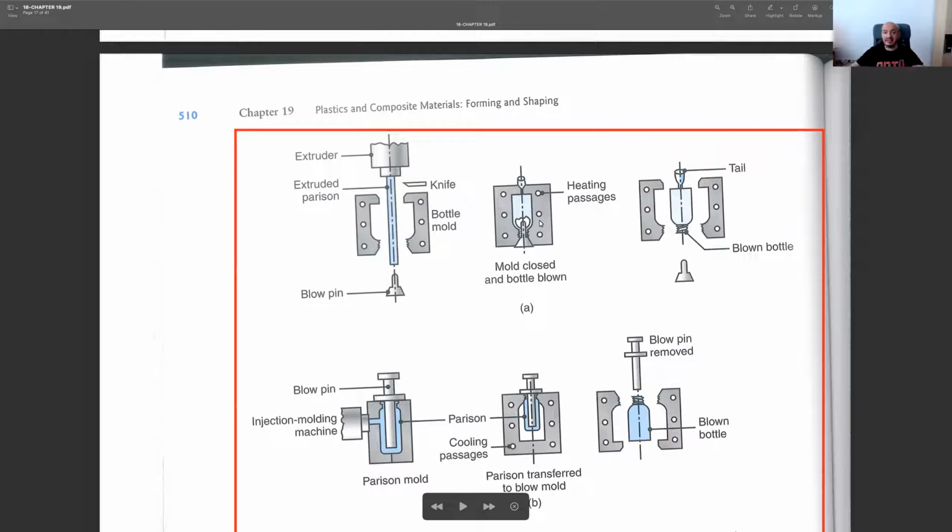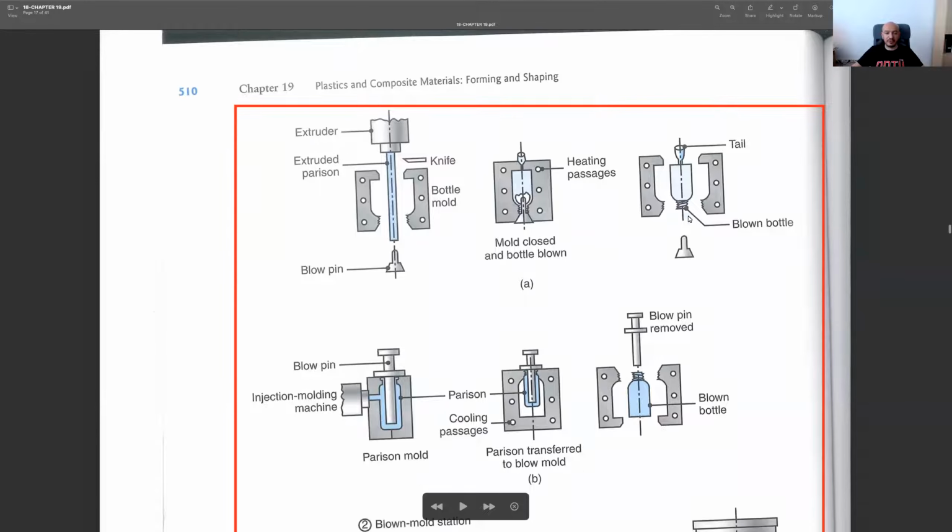We apply air, we increase the volume of this material so that its shape will be deformed, and our material will take the shape of our die. And once this process is over, we can easily open our die set, do maybe some cutting operation, and have the desired part.